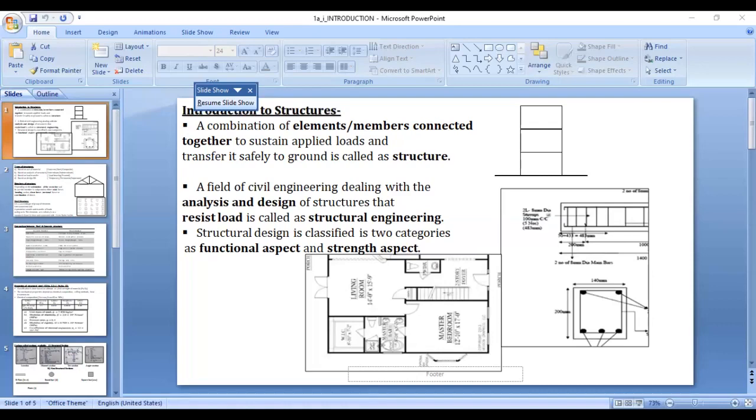Then coming towards the properties of the steel structure, IS 800:2007, page number 12, clause number 2.2.4.1 gives us an idea regarding the properties of a steel structure. Classification is done based upon the ultimate or the yield strength of the material, that is Fu or Fy. The mechanical properties depend upon the chemical composition, the rolling method, heat treatment, etc.